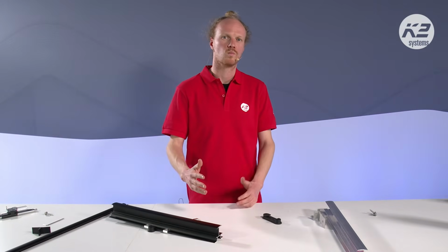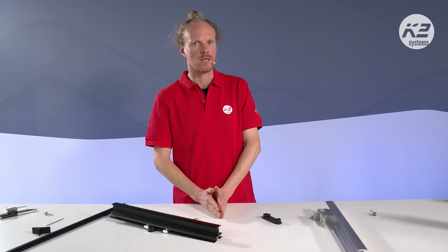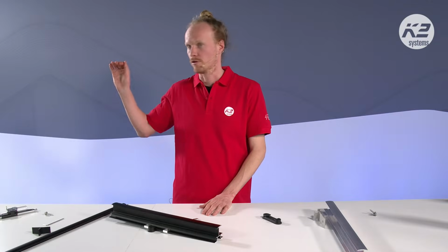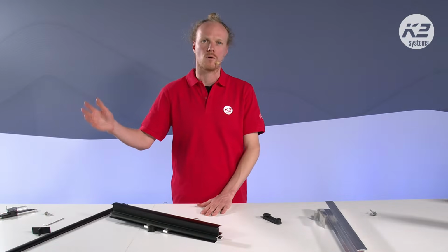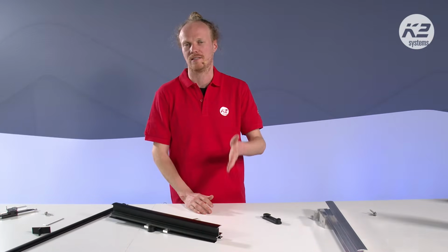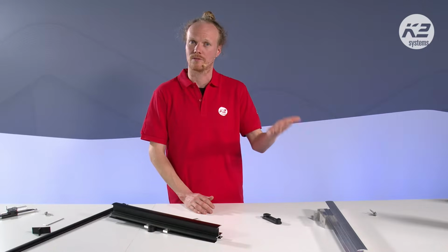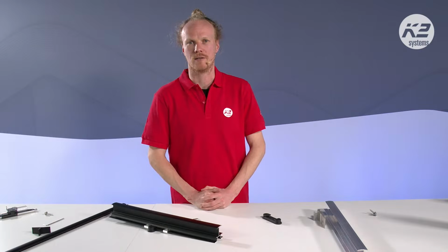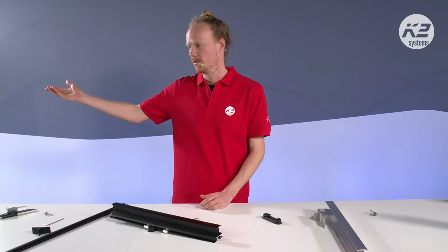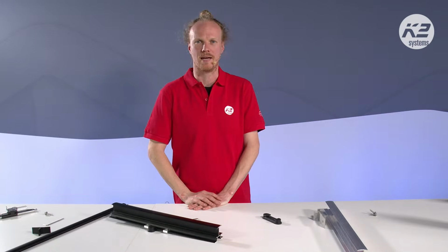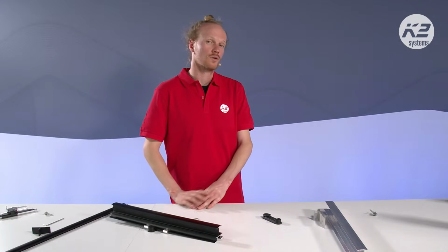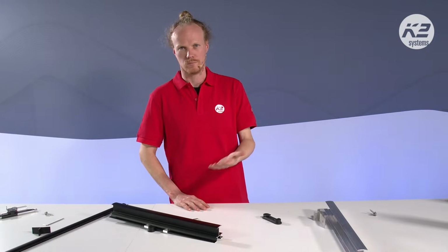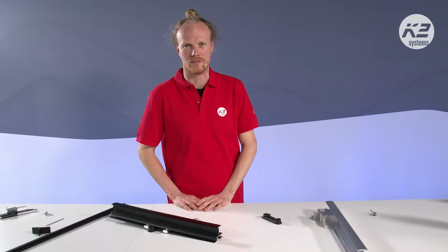And with that, what's also really important is actually whether the panel is allowed to be built in this setup, because the panels and the safety on a rooftop is quite different to the requirements for safety in a vertical installation. If something was to fall, and there are people underneath, then it becomes a very different story than if it was to fall effectively from a rooftop like this. So that's also just something to consider when you're talking about inclination, because the panels fall into a different bracket when they're installed in a different way as well.